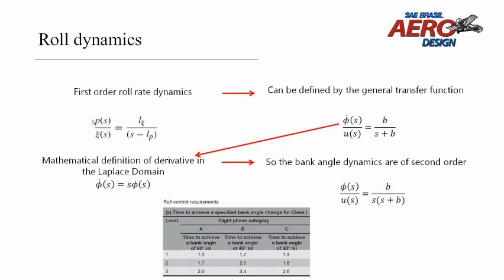For the ailerons design, we can make use of the decoupled equations of lateral motion, whose moments are expressed by letter L. Cook mentions that this would be valid just for the initial 2 or 3 seconds of simulation, and after that, the roll would affect yaw. Roll motion design is slightly different from pitch for the reason that the known transfer function is that of the roll rate, which has a first-order response.